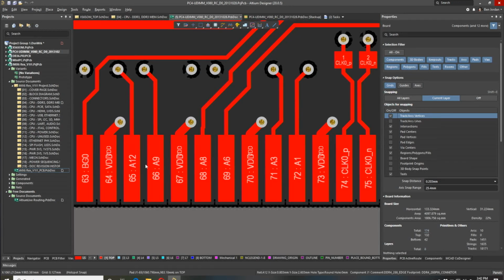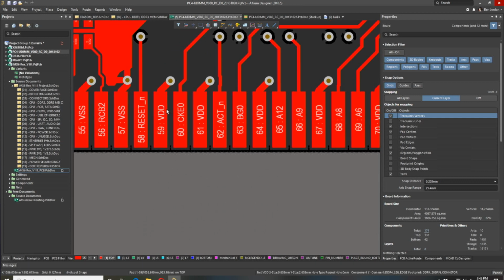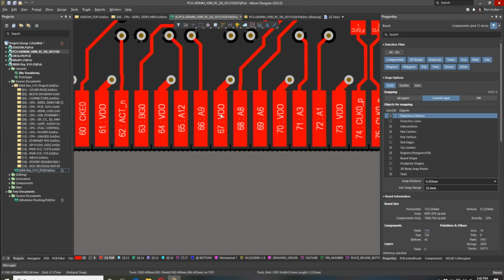because in the middle of DDR4, we have the address and control lines. You see the address lines here. Also, just a note on signal integrity, as we get faster and faster, we have to add far more return and power on our connections. So JEDEC, in their wisdom and working with companies like Micron, defined the DDR4 standard to have every other pin, if it's not a pair, or almost every other pin, be power and ground. So we have very low impedance power and ground connections, and every signal has a return path next to it.